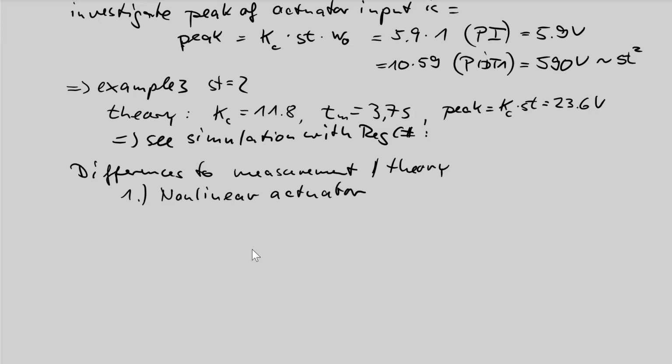The actuator we use is a triac. Triac, maybe you have heard it. A triac is a semiconductor hardware which can do the following: if you have an AC voltage, a triac can switch on the voltage at a later moment than a zero crossing. So the triac switches on maybe the sinusoidal signal here, but can't switch off, it only switches off at the next zero crossing.